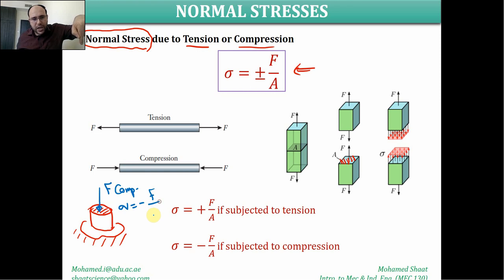The force divided by the area. Which area? This is the cross-sectional area. Your objective is just to calculate the area of this circle and put it into the denominator. You're going to end up with the stress due to that force. But if the force is projected out of the surface, it will be positive, indicating that it is tension.